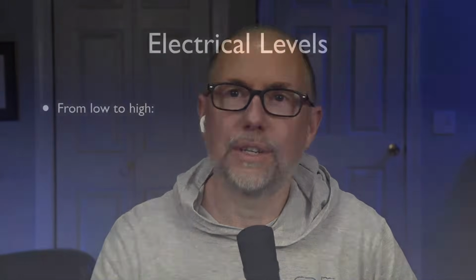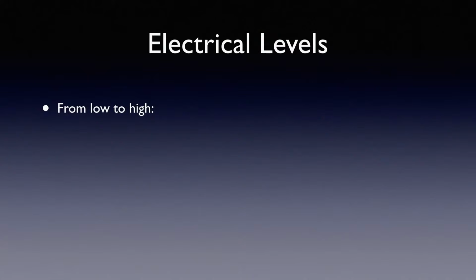So we're talking here about analog audio running over electrical wires as electricity. There are 4 categories of those signals, and they start with the smallest one, which is mic level. Mic level is balanced and tends to have low output impedance and somewhat moderate input impedance.